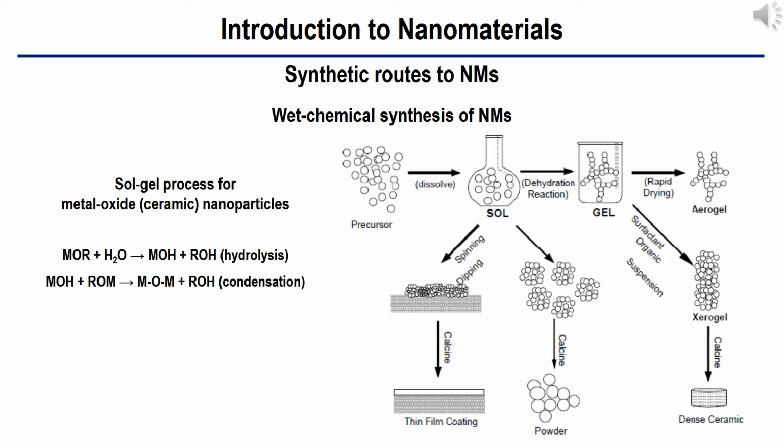Sol-gel processing refers to the hydrolysis and condensation of alkoxide-based precursors such as tetraethyl orthosilicate. The reactions involved in sol-gel chemistry are based on the hydrolysis and condensation of metal alkoxides. The sol-gel method of synthesizing nanomaterials is very popular amongst chemists and is widely employed to prepare oxide materials. The sol-gel process can be characterized by a series of distinct steps. 1. Formation of stable solutions of the alkoxide or solvated metal precursor.